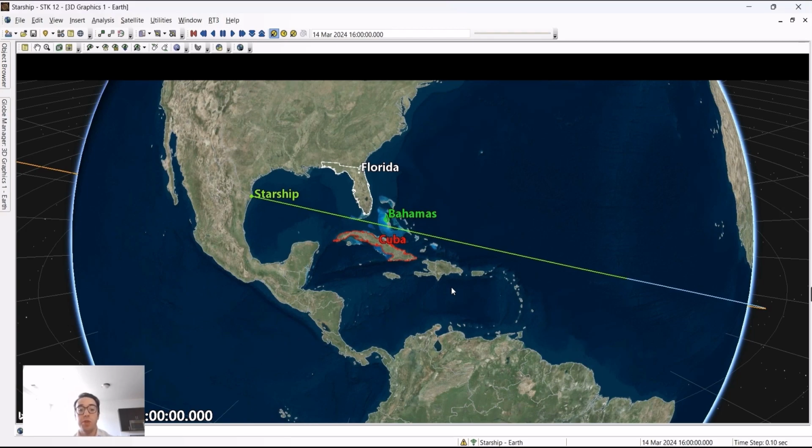Typical examples of the uses of Analyzer in STK include positioning satellites to obtain optimal coverage, predicting ranges for fuel requirements due to variations in satellite launch positioning, and configuring transmitters and receivers to maximize communication bandwidth. And in our case, we're going to use STK Analyzer with Astrogator in the case of a launch, specifically a launch to GEO.